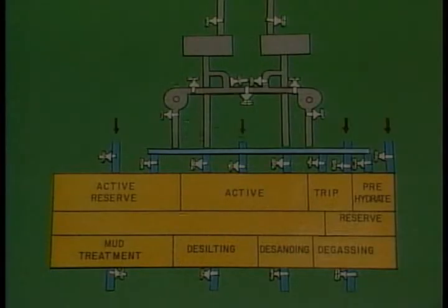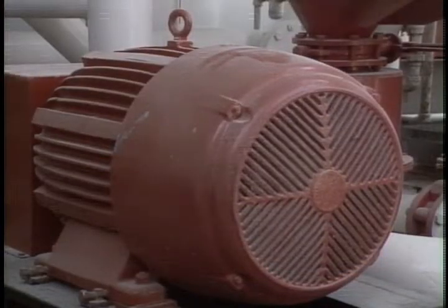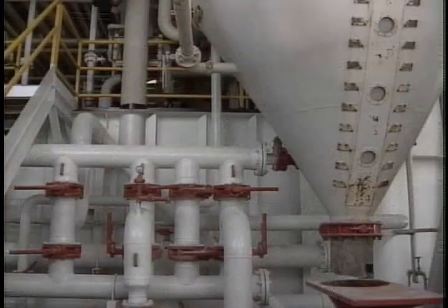The other valve from each tank connects to another suction manifold that we'll call the transfer manifold, and it ties directly to 2 other low-pressure centrifugal pumps called mud mixing pumps. These mud mixing pumps output to a series of pipes and valves that allow you to direct the fluids to either the mud jets in the mixing room or directly to any one of the pits.